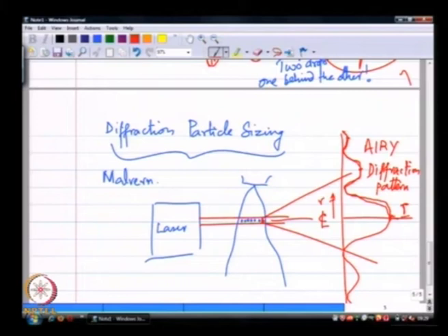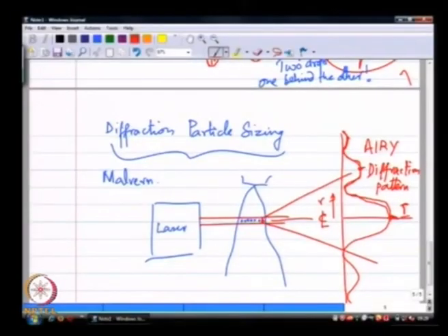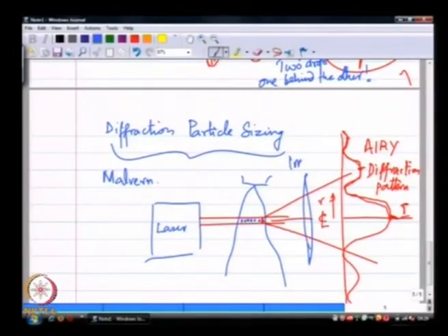From a spherical drop, this Airy diffraction pattern has these clear peaks, and these peaks are directly related to the drop size. So, remember, the diffraction creates an angular diverging pattern. So, again with some appropriate imaging optics, it is usually just a single lens that is enough, and the detectors are semicircular arrays. I mean the Airy diffraction pattern for a circular drop in a laser beam is